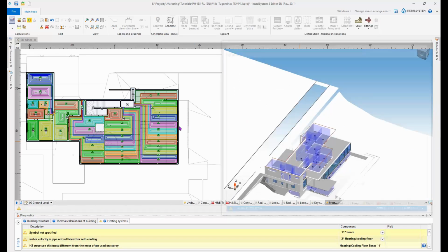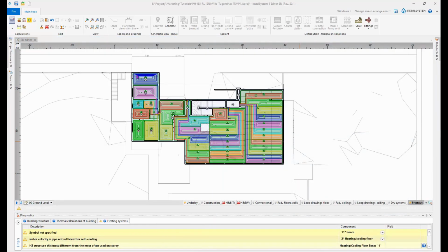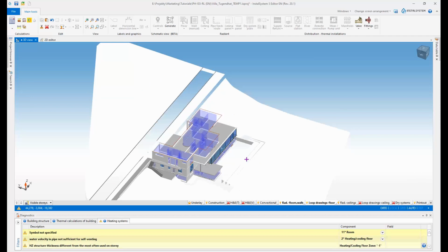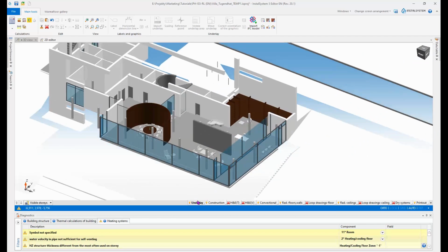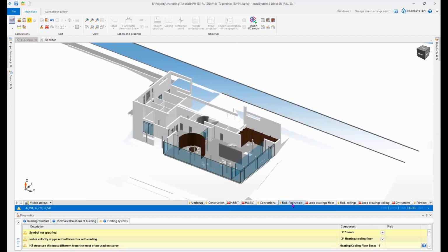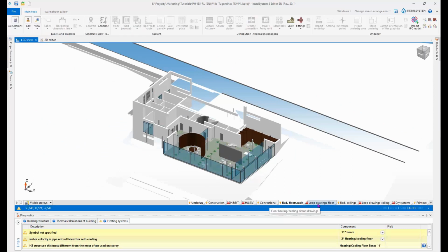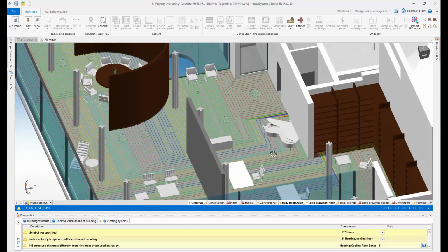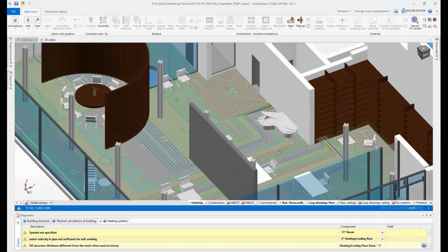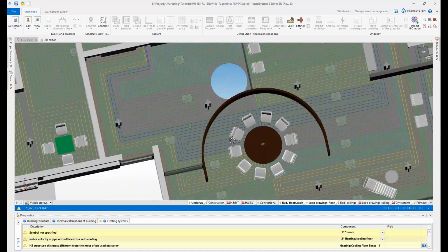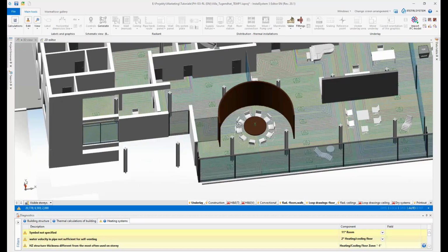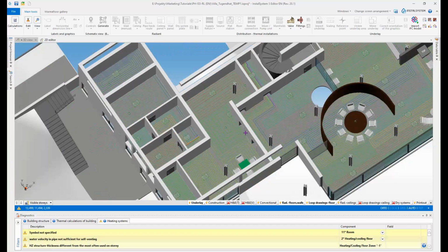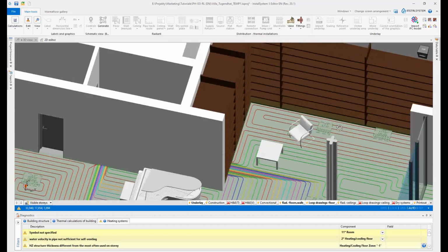Maybe let's open the 3D view on the whole screen. And let's use this underlay view, and by holding Control key I will also select 2 more scopes, radiant floors and walls and loops drawings. So these 3 scopes are selected, and now we can check it on the 3D view. You can also check that opening in a slab. And this way we can analyze all the rooms one by one. You can see the library.